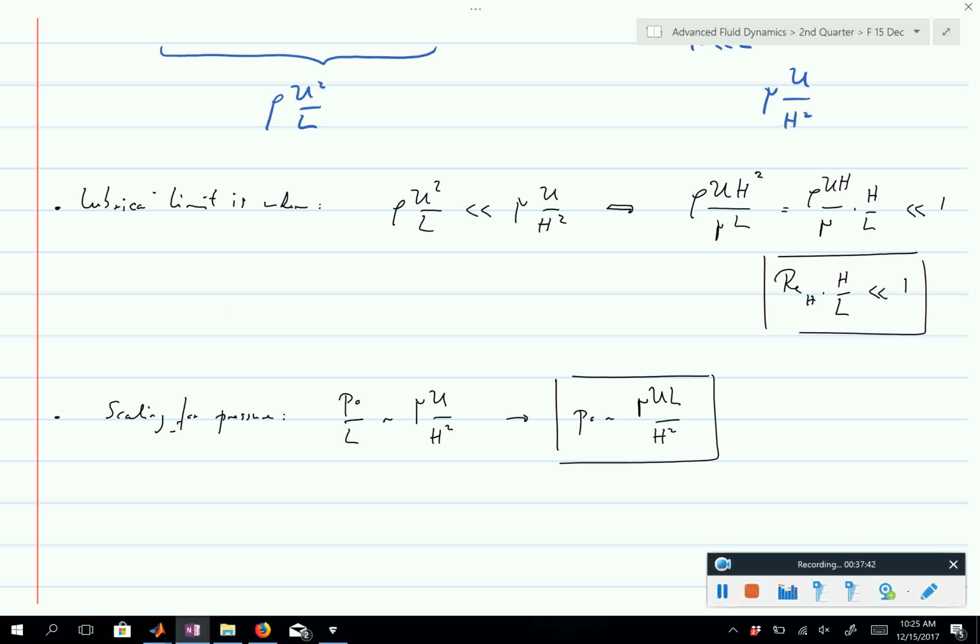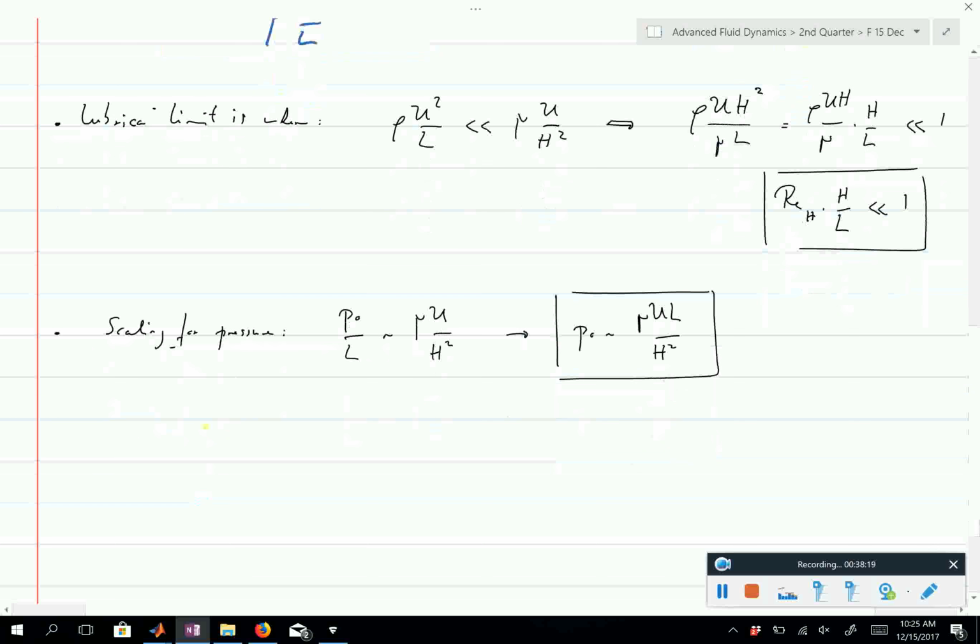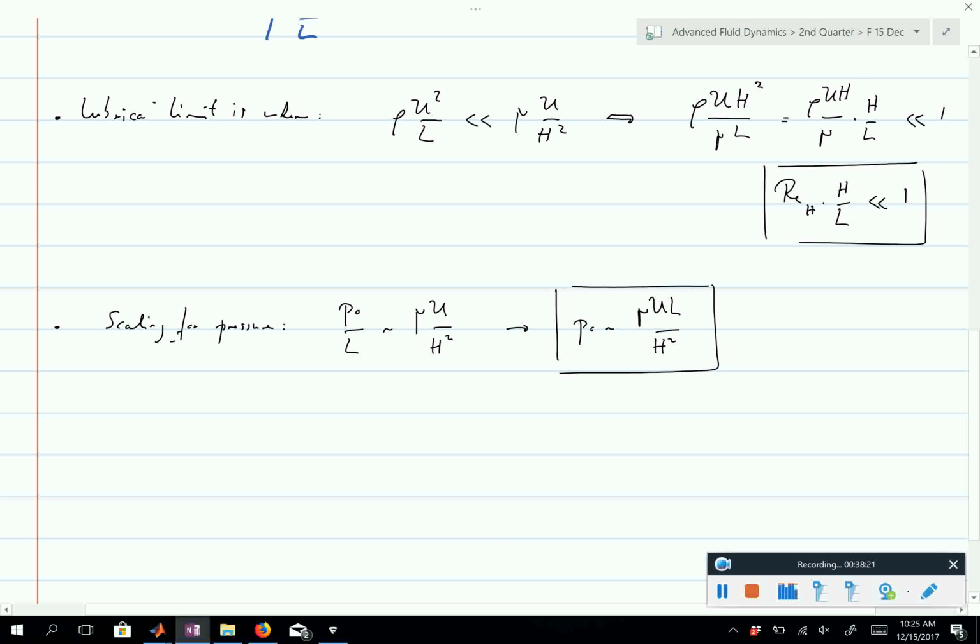Atmospheric pressure, exactly. You have an interface. The interface is relatively flat, so when you apply a boundary condition, you know that the pressure in the fluid is going to be the atmospheric pressure, and then across, you have very small distances to the wall, and you have no flow in that direction, so you don't expect much pressure change. So actually, the pressure inside of the fluid is mostly just atmospheric pressure. But in other cases, you'll see that if pressure does develop in a lubrication layer due to some pushing down, due to flow also in the V direction, then the pressure can become quite large. That's the whole basis for air bearings.